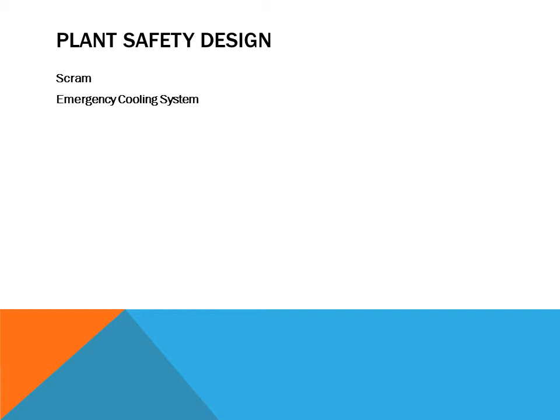The other feature that this plant had was the auxiliary feedwater pumps. Auxiliary feedwater pumps provide secondary water to the steam generators, which we discussed earlier. This water is used to provide a heat sink, so water circulates through either via natural circulation or the reactor coolant pumps through the steam generators. This feed water comes in at a lower temperature and cools the primary coolant, allowing it to keep the temperature of the primary down.